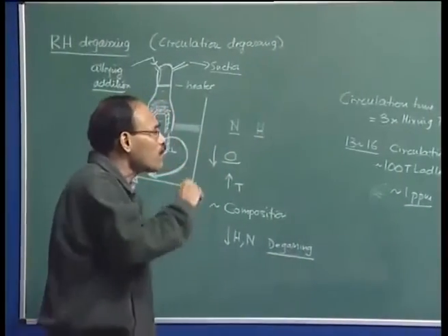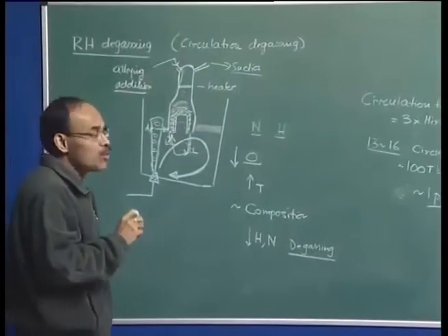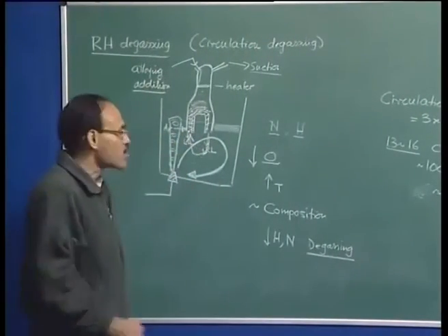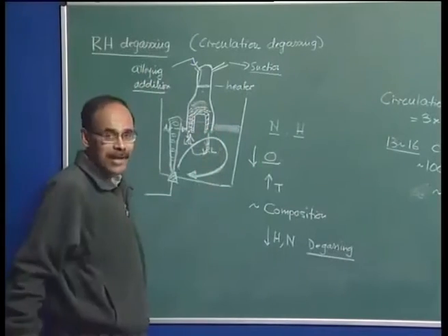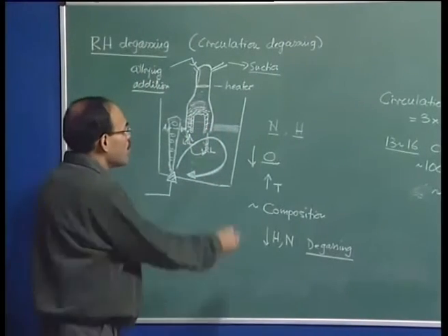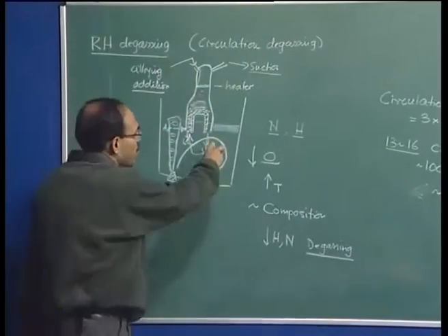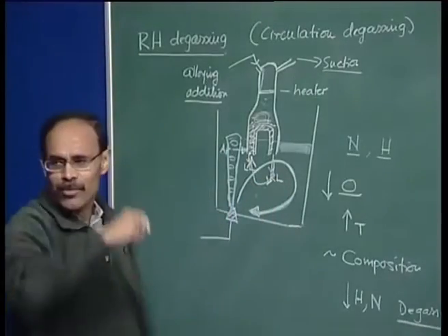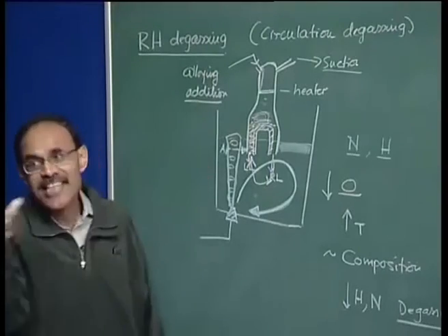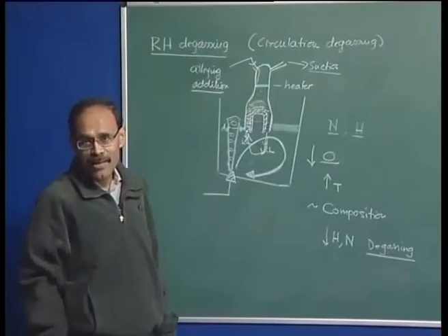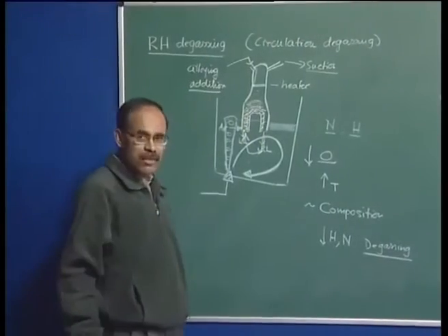What are the sources of inclusions? The sources of inclusions are basically due to entrapment of the deoxidation products or entrapment of the slag in the melt. For example, I may have some slag particle, I have an intense stirring, and that slag particle may be entrapped, and it may never get floated up from the molten steel system. So final steel cast will show that yes, indeed slag particles have been entrapped at certain stages of steel processing.